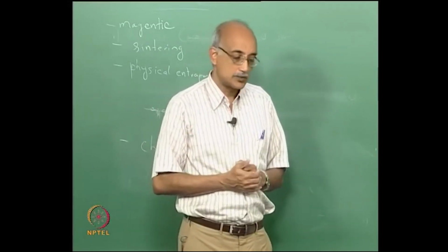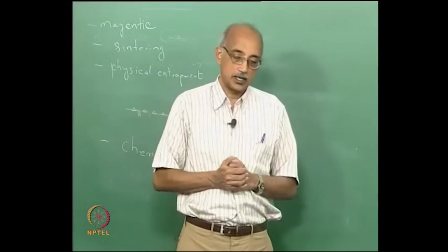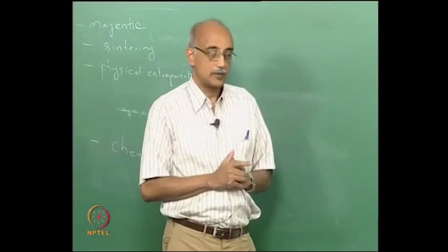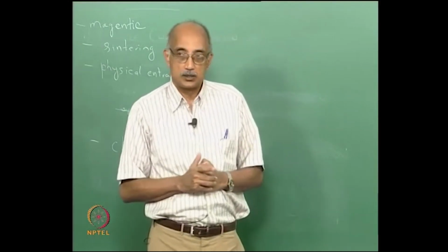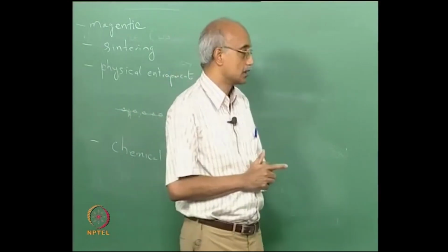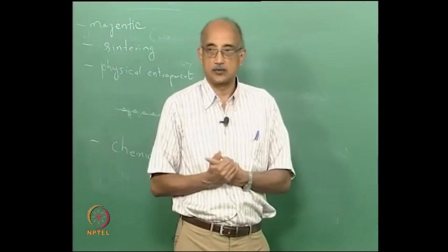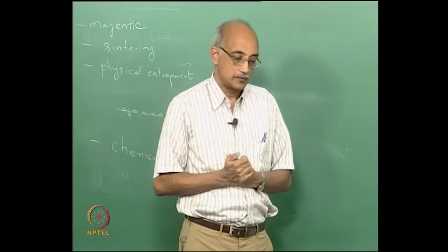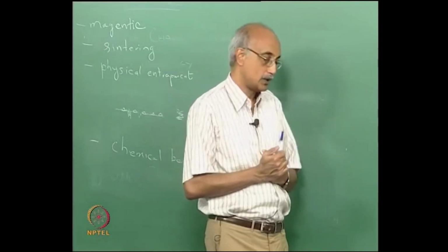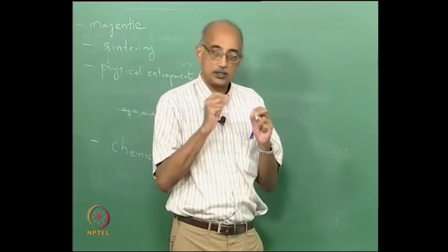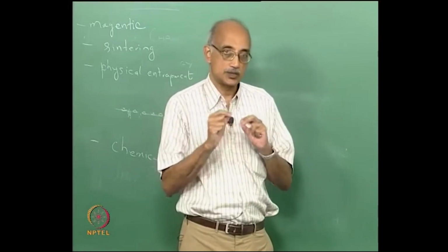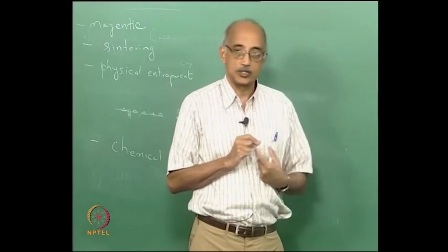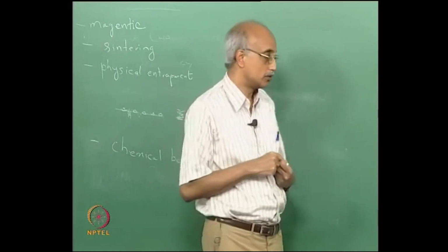Van der Waals force, as we again discussed in the last class, is characterized by a parameter called the Hamaker constant. The Hamaker constant is the most fundamental representation of van der Waals forces binding two surfaces. The Hamaker constant, therefore, plays a huge role in determining the force of adhesion between two surfaces, particularly under dry conditions where some of these other forces that we have been talking about do not apply.